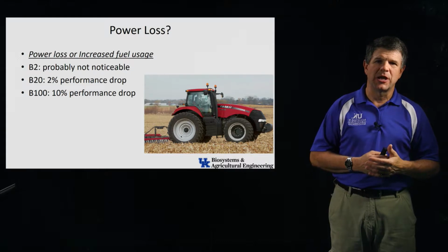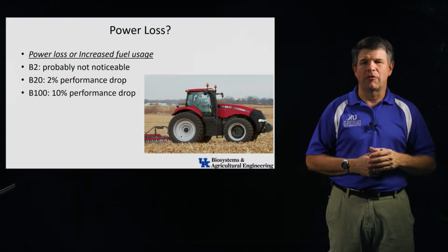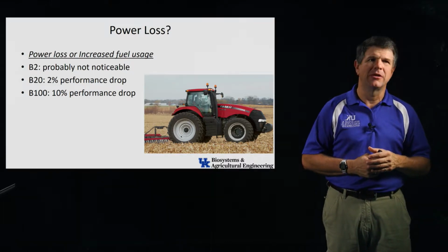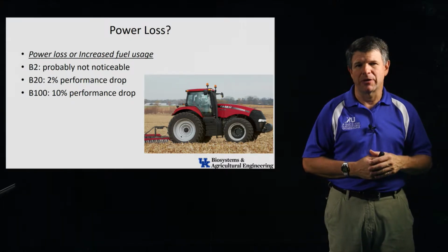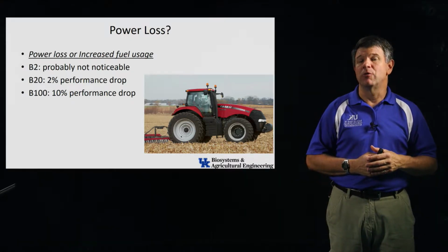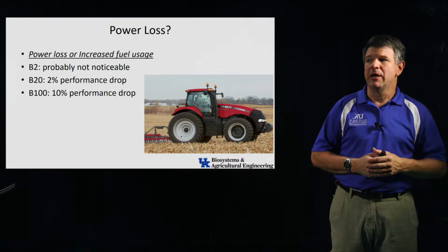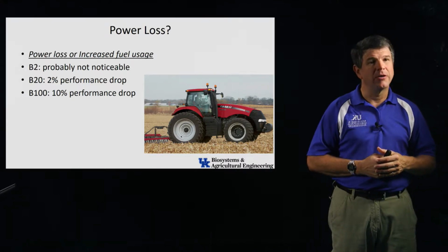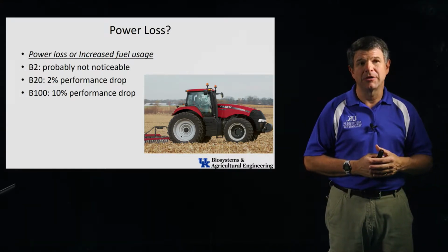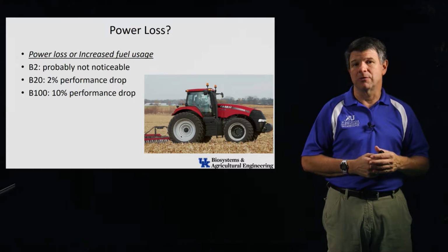If it's 20%, I'm going to notice about a 2% drop. Will I notice that? I might notice a little bit less power going up a hill, or I may notice some fuel mileage difference or something like that. 100% biodiesel, I'm going to notice a 10% difference. That's going to be significant enough for me to notice what's going on.